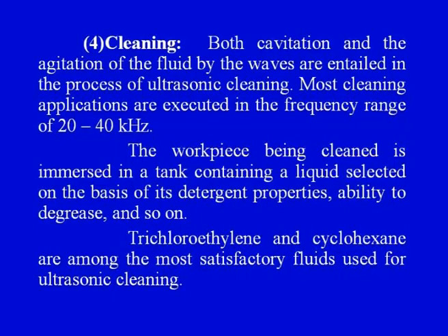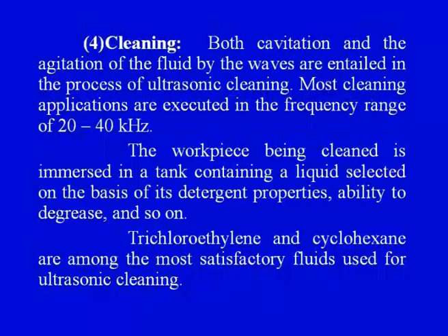Number 4, cleaning. That is a very special type of application. Let us see that. Both cavitation and agitation of the fluid by the waves are entailed in the process of ultrasonic cleaning. Most cleaning applications are executed in the frequency range of 20 to 40 kilohertz.